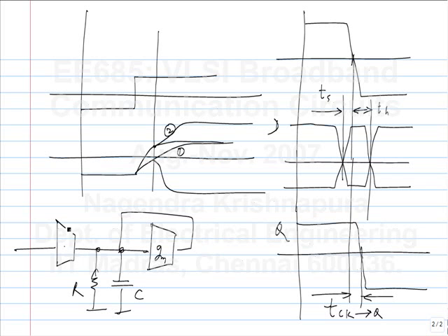So basically this differential pair turns off and this turns on. That's what I'm saying, but it takes some time. So the current that is being pushed into this node, the RC parallel combination, will be a linear combination of this VD, the input voltage that's applied, and the output voltage that is present, VQ. So it is not just a function of VQ. What you would like is, during the sampling phase, this voltage depends on VD, and during the hold phase, it depends only on VQ. So it samples and then regenerates, but that doesn't happen.